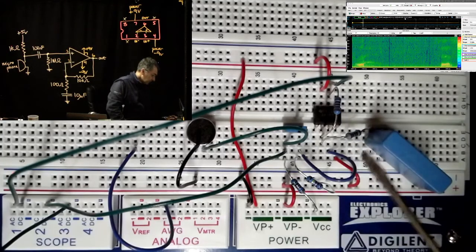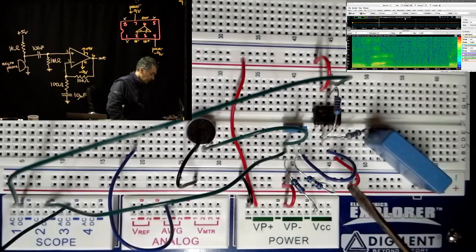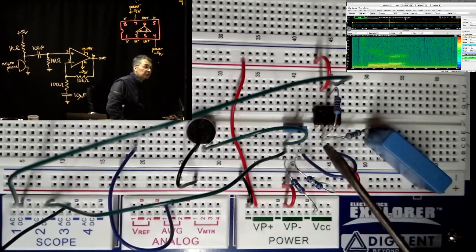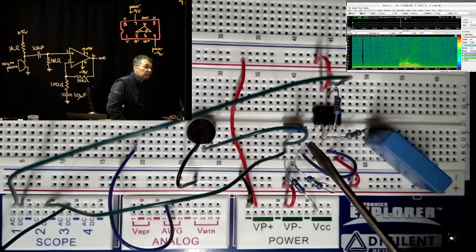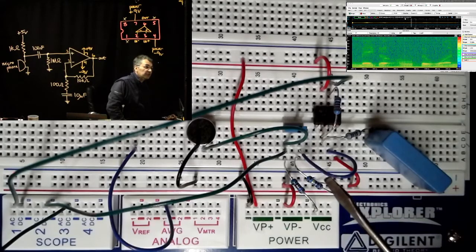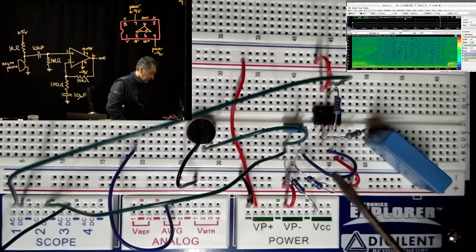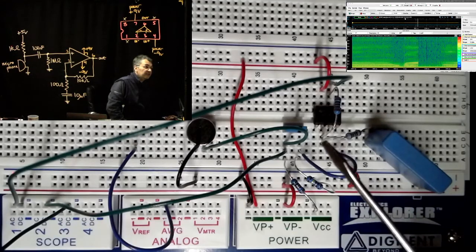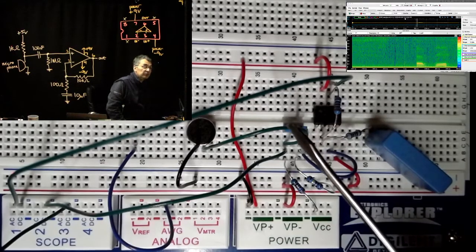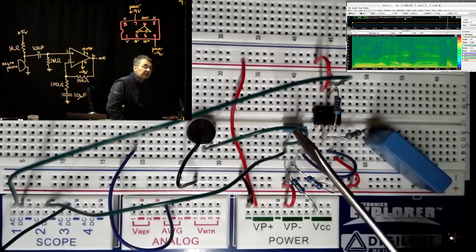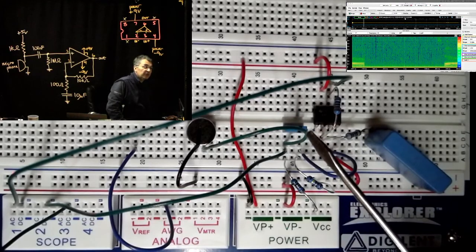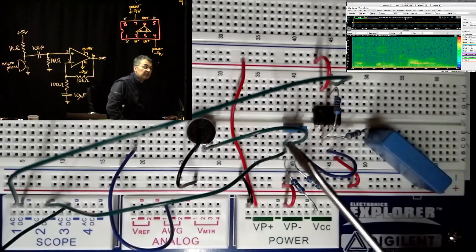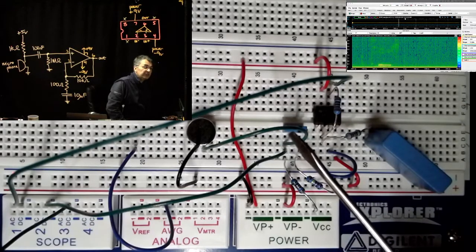schematic. So this little blue jumper wire brings us over to this point, from which we have the 1 megaohm resistor, that's this guy, goes down to ground. It's hard to see that it plugs into ground, but it does. It plugs into this ground row here. And then we have this small blue 100 nanofarad capacitor, going from that same column over to here.